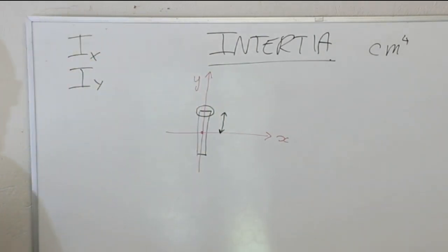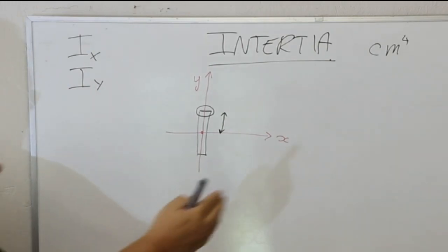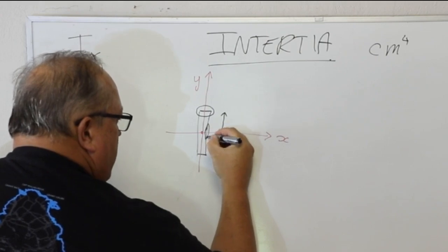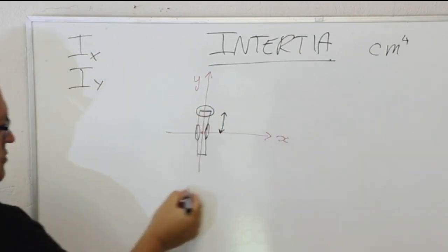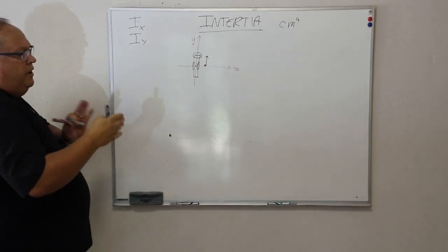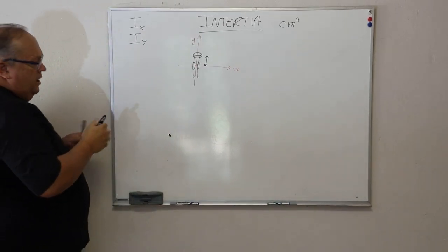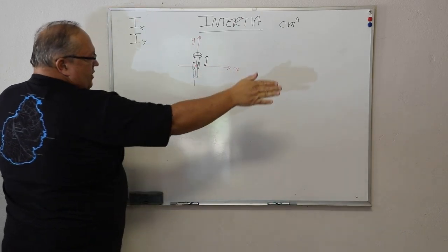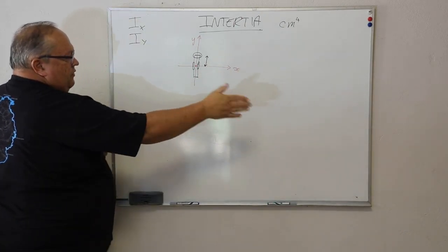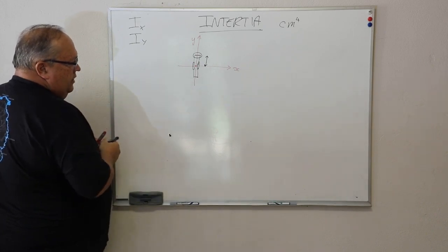In this case it would be the y value. So my Iy value would be increasing. If I look in my x direction, all my material is extremely close to my vertical axis. So I do not have much strength in the horizontal direction. And therefore when I'm holding that profile up like this, it's rigid vertically, but it is floppy in the horizontal direction.